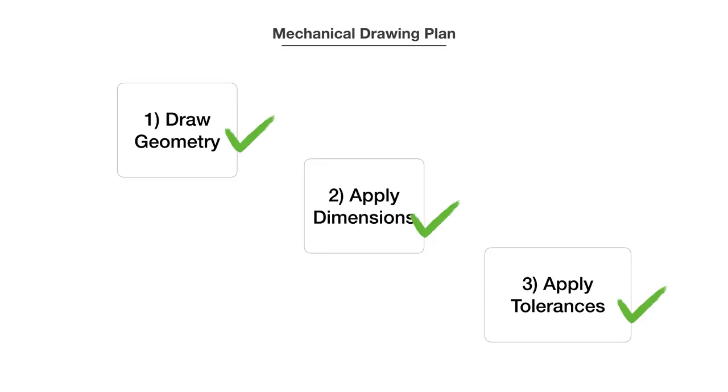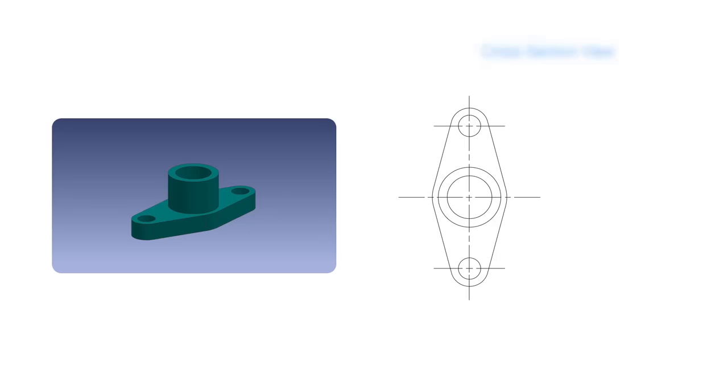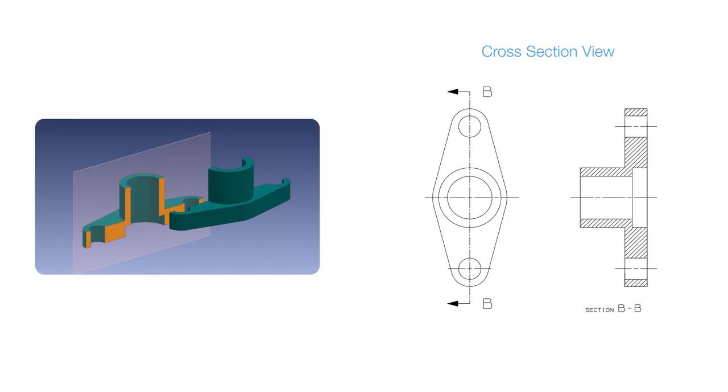Now that we're done with this drawing, let's flesh out our mechanical drawing toolkit with some alternate views that are better at showing certain features. First, I'll talk about a cross-section. Sometimes it's good to see the inside of a part. So you might imagine a plane cutting a part in the region of interest. Here is that flagpole holder part from earlier. And then you have the plane called the cutting plane and go slice it open.